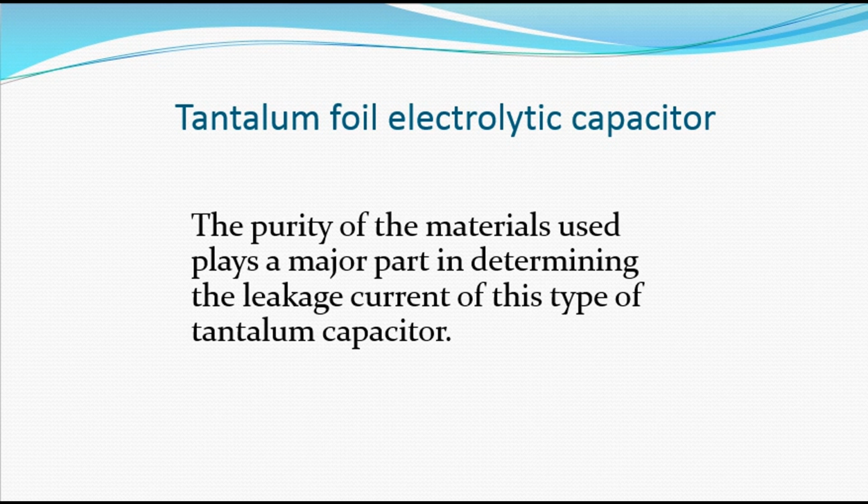I will explain and define what leakage current is all about in each of the capacitors that we are treating in this video. So in that case, what I want you to understand about this tantalum foil electrolytic capacitor is that the purity determines the leakage current of this type of capacitor.